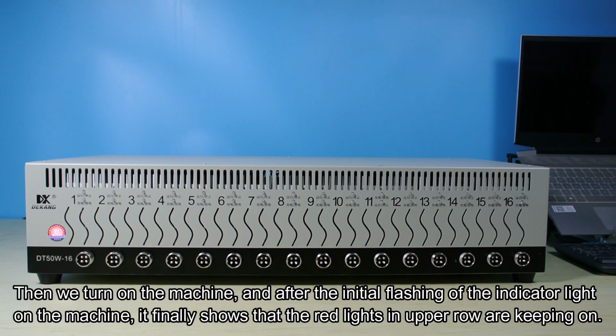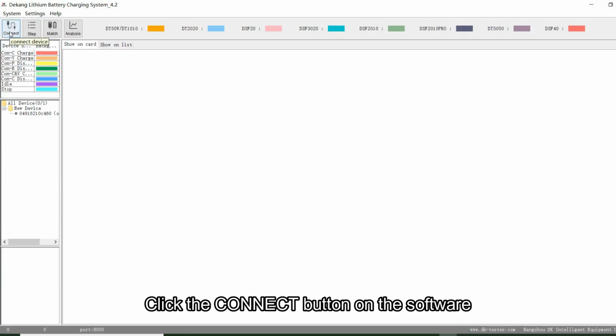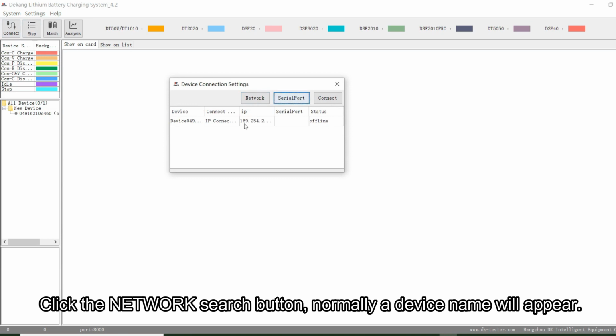Then we turn on the machine, and after the initial flashing of the indicator light on the machine, it finally shows that the red lights in the upper row are staying on. Click the Connect button on the software. Click the Network Search button. Normally a device name will appear.